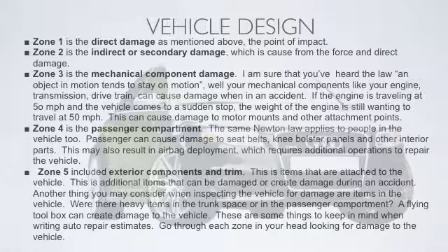And then you've got to think of the mechanical components, and just like Newton's law, what's in motion tends to stay in motion. Well, if you think of a motor bolted onto a frame, if it wasn't bolted in, and you hit something, what's going to happen? That motor is going to want to continue going forward. So you may have to look at some of the damage going the opposite direction. Where the motor's bolted on, you may have to look for some of the damage going forward.